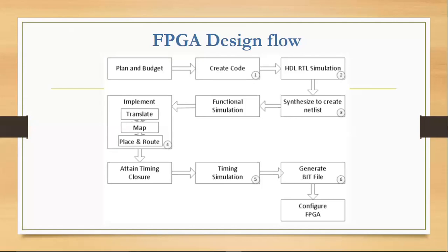The next step after getting the RTL schematic is to synthesize and create a netlist. Synthesis is the process to create a netlist and analyze the hierarchy of our design. To verify the functionality of the design, we need to simulate it. Then we can get the simulated waveforms according to the given specifications. That's the next step after the synthesis.